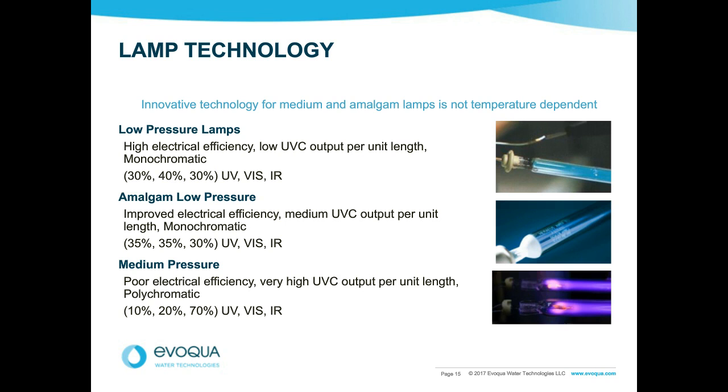We have a very wide variety of applications, from pristine RO permeate, really high quality wastewater destined for direct potable reclaim. We have lots of stream or ditch discharge applications where the UV is in a pipe disinfecting 6, 8, 10, 12 or even 22 million gallons per day of oxidation ditch or primary and secondary treated effluent. We have a number of combined sewer overflow installations where we are disinfecting the storm surge from a high rain event. It needs to be properly sized.